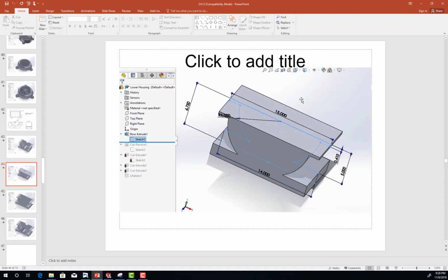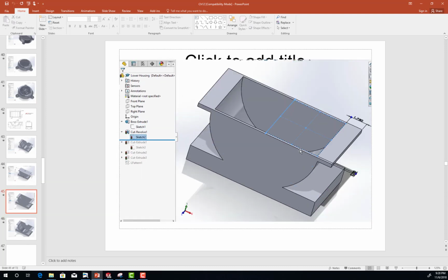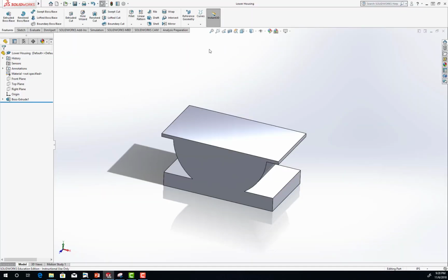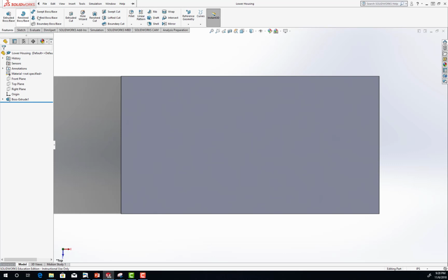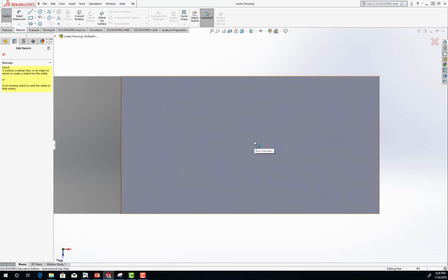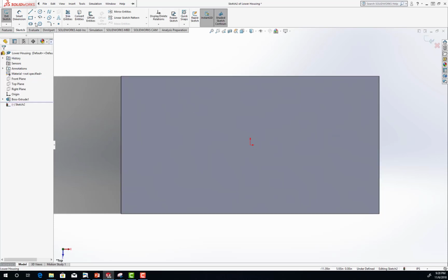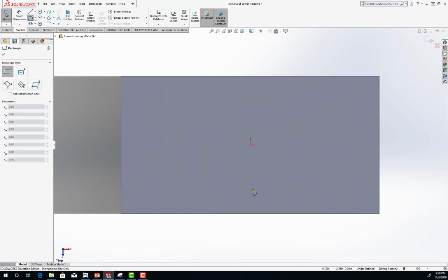And we are going to do this square part, then do a revolve cut. And let's go back to SolidWorks, and I'm going to go to the top view and make that a square. So I do a sketch, select the sketch, and select the top plane, and do the square. So I am going probably rectangle, not 100% sure. So anyway, I'm going to select this part and recognize from the center, so I don't need to add relations later, and put it like this.